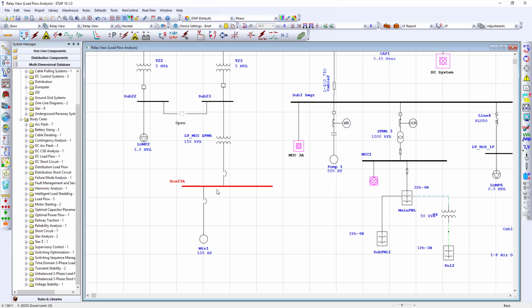They're rolling out new production lines, and there needs to be the ability of having more motor loads connected to this MCC. So what the scope of work for consultant A involves is, number one, updating the proposed changes to the ETAP model with the additional motors, making sure that the protection and the coordination between the main and the load breakers is properly set, and at the same time upgrading the transformer.